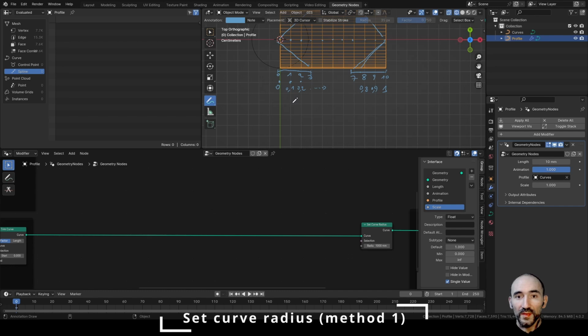And because we are talking about distance and length, we can say if the length of these points is less than a threshold, in this case 0.3 for example, I want to multiply the radius by values from 0 to 1, considering a range from 0 to 0.3, my threshold, remapping in a ramp from 0 to 1, okay, because 0.3 is the length of my curve, but I need to remap this range of values in a range from 0 to 1 to multiply the original radius by 1 from this point to this point